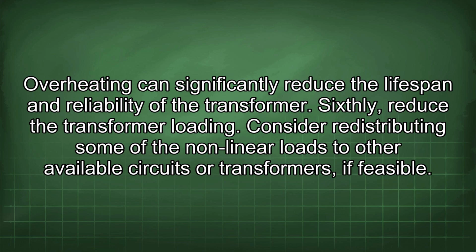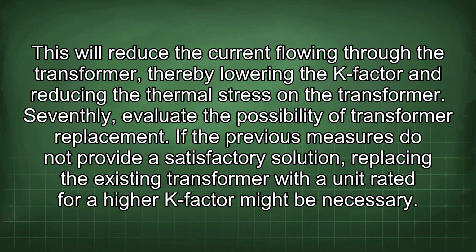Sixthly, reduce the transformer loading. Consider redistributing some of the nonlinear loads to other available circuits or transformers, if feasible. This will reduce the current flowing through the transformer, thereby lowering the K-factor and reducing the thermal stress on the transformer.